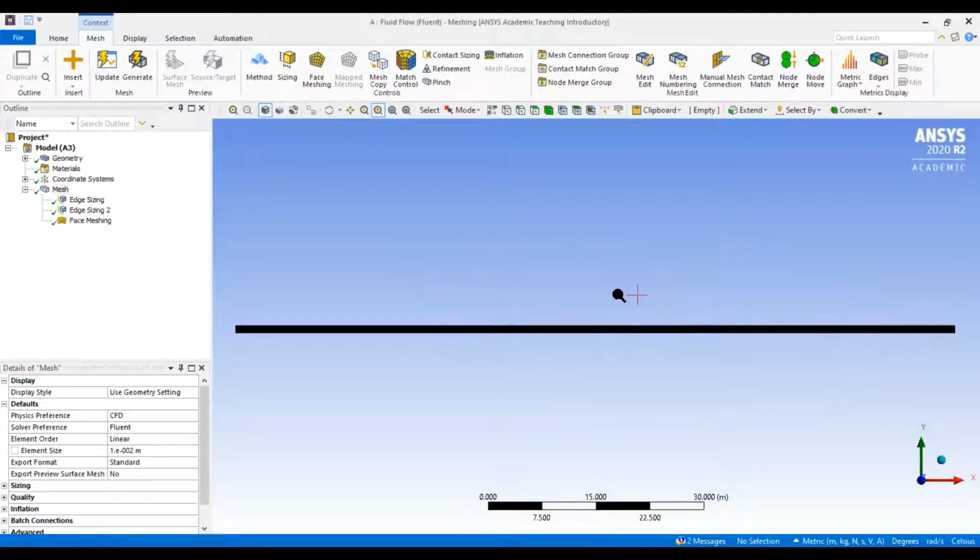So now that we have our mesh finally generated, we can do one more important step. Before you move on, you need to select each section and give it a name. And I'll show you why you have to name all of your sections in a second. So the way that you're going to name each surface, you're going to go back to edge as we did before, select the edge that you want to name, right click and create a named section.